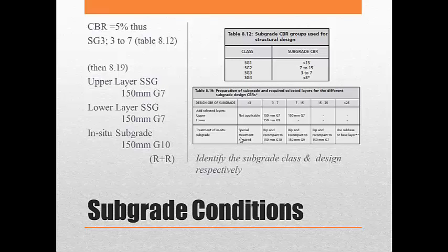The higher the value of the CBR, little or no subgrade would be required. Thus, after we select our catalogue design, we are going to add our selected layers, and we will, when necessary, rip and recompact the in situ subgrade, or if necessary, we will stabilize it to reflect an acceptable CBR.